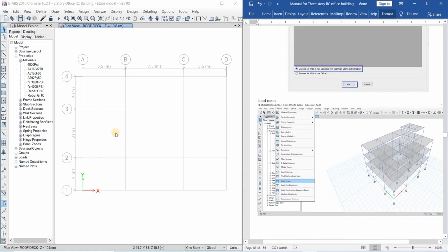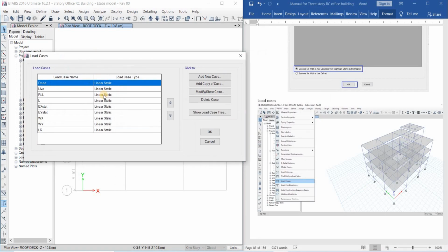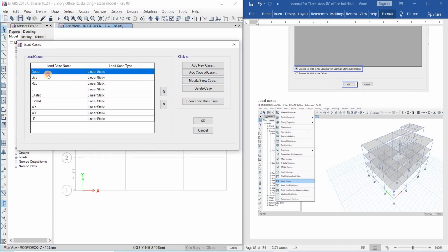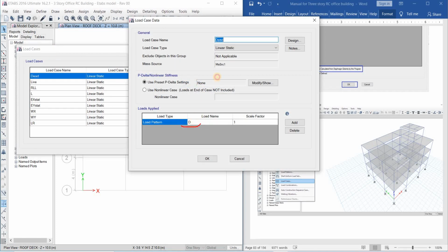Okay. So now, let's go to load cases, define load cases. So your load pattern is equivalent to the load case. But in our first step, we renamed this one as dead, this one as D, and this one as SD. So we'll just rename it again here in the load cases. So I modify that, it should be the same. That is just text, click OK.